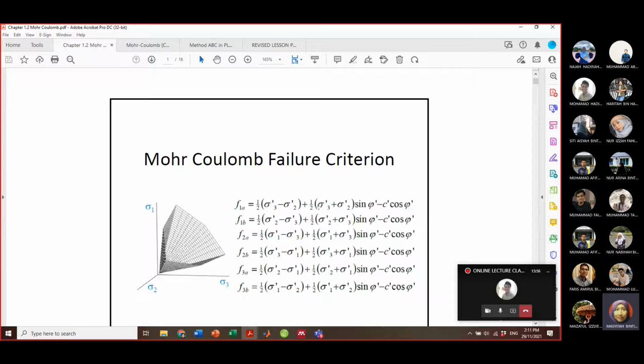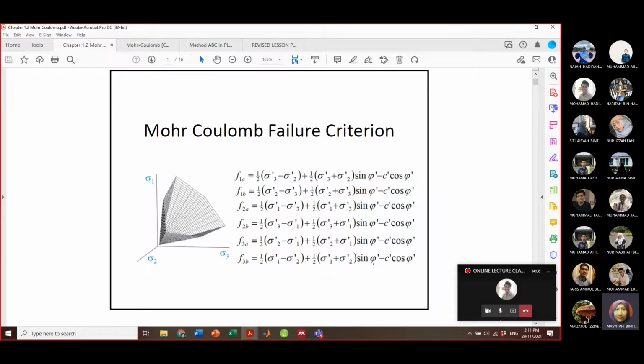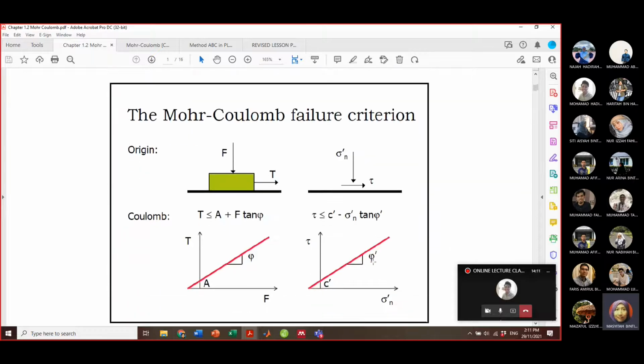So right now you may see the relations between the effective internal friction angle as well as the internal cohesion of the soil, and how they relate. This is what we are trying to explain with Mohr-Coulomb. If you remember, when we dealt with the failure of the soil, when you are conducting a triaxial test, for example, you may have different failure behavior in UU, CU, and CD.